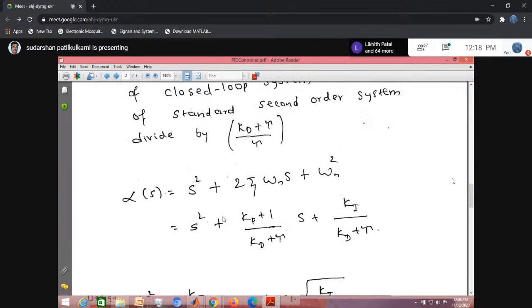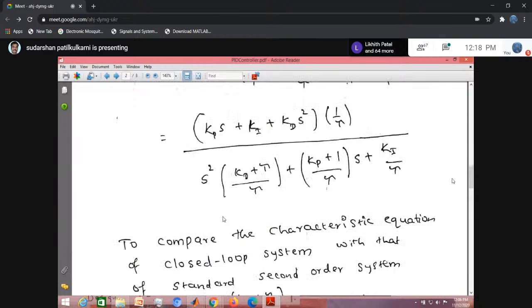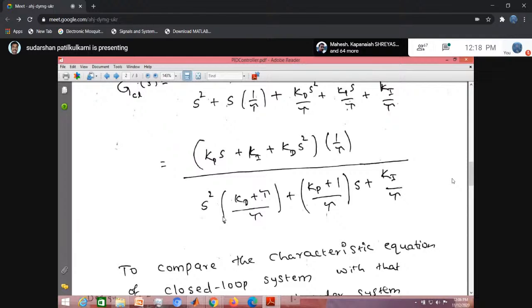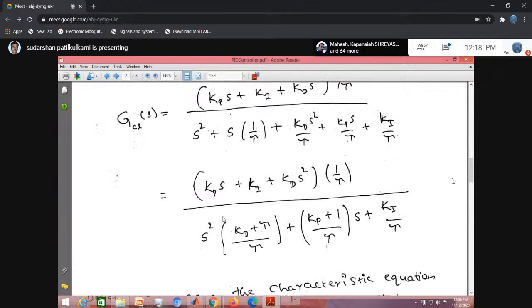You should be able to derive the step response of the standard second order system and expressions for time domain parameters: rise time, overshoot, settling time, and how the pole locations are related to all those parameters. And then the stability definition, theorem, and the Routh-Hurwitz test for stability, and special cases in the RH test.